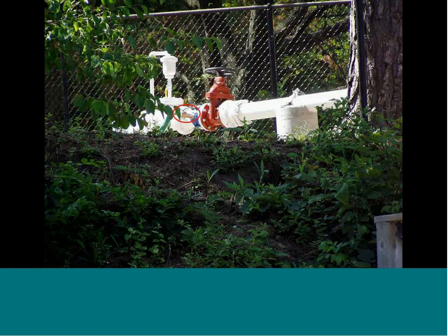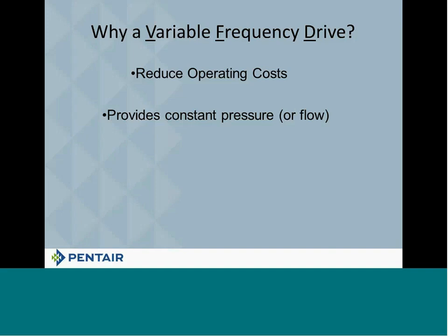And if somebody forgets to open up that valve, and they've got the other valve closed, the drive says, you know what, we're hitting the pressure we're supposed to, we better go to sleep, and it would put the drive to sleep. It was just a safety precaution so that guys wouldn't forget to do what they were supposed to do. All right? Now, other reasons then, we want to reduce costs, we want to produce a constant something.